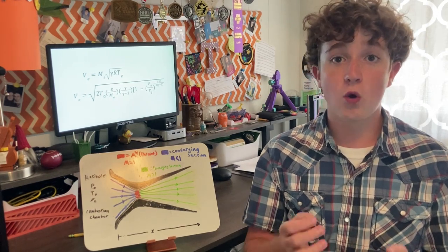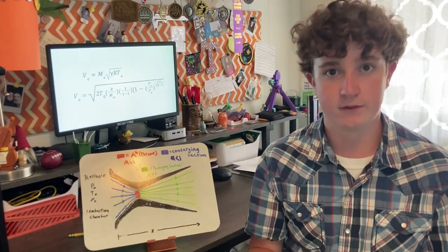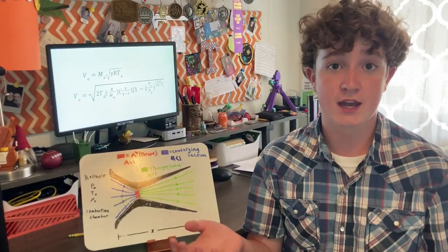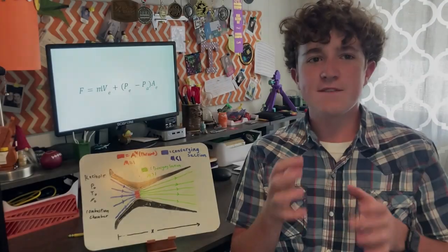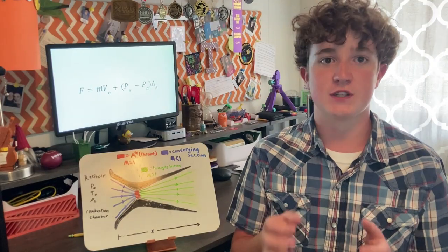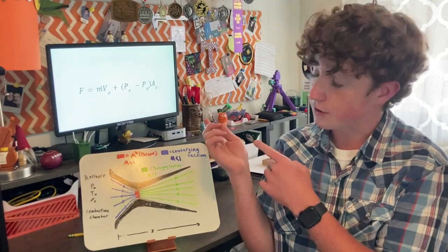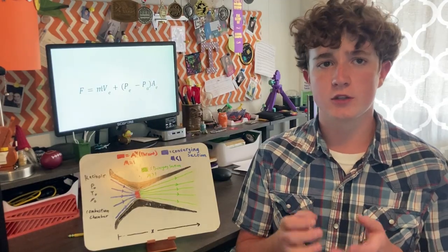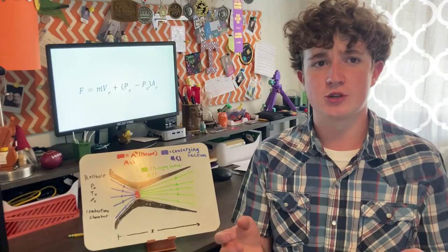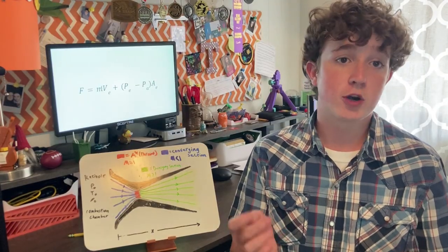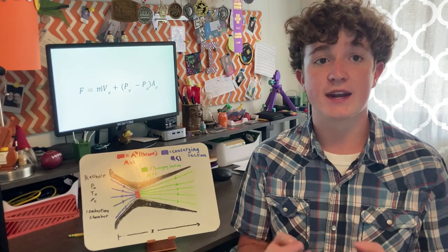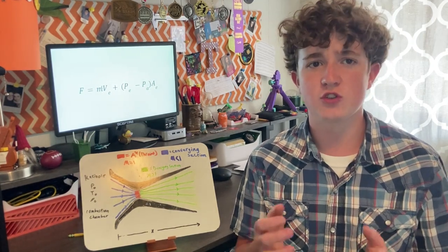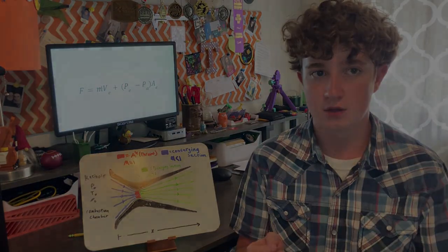This explains why a cold gas thruster will always have a slower exit velocity compared to a conventional, high temperature rocket, such as the Falcon 9 rocket. Exit velocity is so important as it increases thrust. In the thrust equation given here, we can see that it is largely based off Newton's third law of motion. The second term can largely be ignored, as ideally the exit pressure and the ambient pressure are the same, so the term equals 0. Therefore, we can see that a higher mass flow rate and a higher exit velocity will increase our thrust, which is why nozzles try to increase velocity so much.